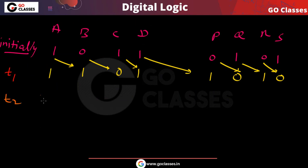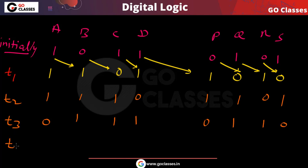After one more clock pulse, what will happen? Very simple, this one again will come here. Then you have 1 1 0, and then 1 1, and then 0, and then 1. After the next clock pulse, this 0 will come here also. So like this 1 1 1, and then you have 1 1 and 0. After one more clock pulse, this one will come here, then 0, 1 1, and then 1 0 1 1. Now you can notice, that's it.